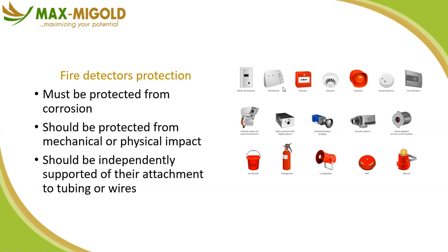So again, we should ensure that they are protected from mechanical or physical impacts. Don't have your panel positioned in a place where the boom lift or the work elevated platform can hit or collide with this equipment. And of course, they need to be supported independently during installation. Next slide, please.